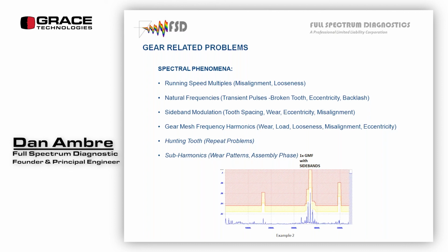They're all running in the same area, and I can look at them statistically as a family instead of just a one-off type thing. And the beauty of that is if something's out of family, you're going to see it much quicker. Most software out there will have statistical bands or the ability to do that. In addition to taking your normal data, it's just another set of alarm bands. You have standard ones, and then you'll have another one that says, hey, is this in family with the rest of the gearboxes? It's a very helpful tool.